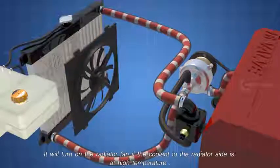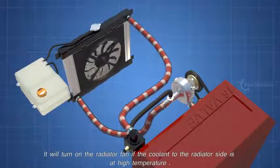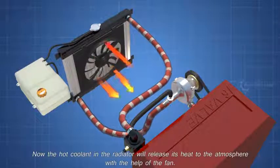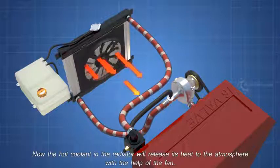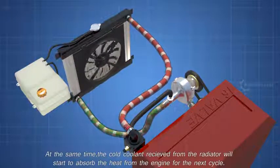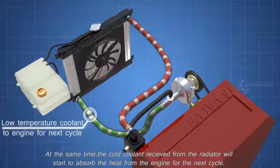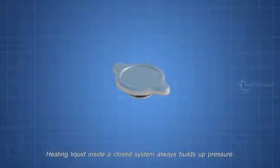It will turn on the radiator fan if the coolant on the radiator side is at high temperature. Now, the hot coolant in the radiator will release its heat to the atmosphere with the help of the fan. At the same time, the cold coolant received from the radiator will start to absorb the heat from the engine for the next cycle. Heating liquid inside a closed system always builds up pressure.